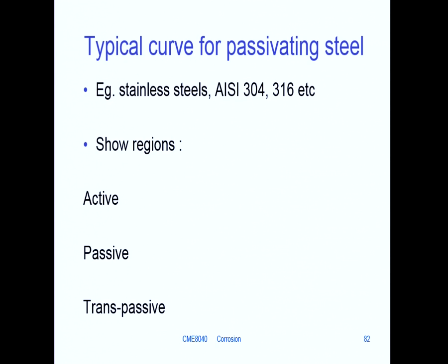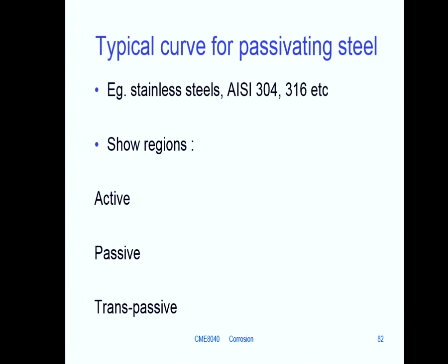So the scan has gone from the cathodic through to the free corrosion, starts to corrode, then passivates, at which you get very little current, despite the change in potential, and then eventually you get a pitting potential somewhere there. The scan is that way. This is your E-corr.